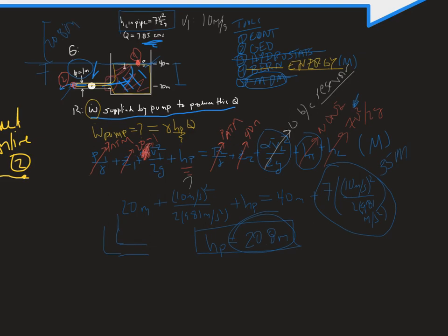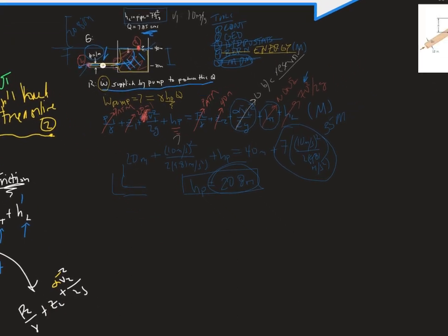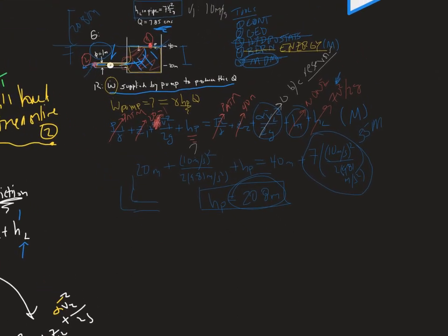Sorry about that. Let's go ahead and finish the problem. So this is how much energy the pump is giving the fluid in order to make that happen. Right now, you might care more about it in terms of watts or something along those lines, so we'll go ahead and solve that. That's gamma HPQ.